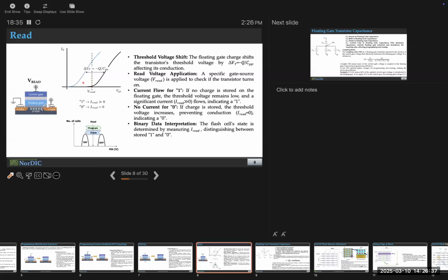Does that make sense? So just looking at the difference in current, you could sense it. And isn't that the story everywhere? Even for the ferroelectric transistor, that was the exact same story. For positive polarization, you have some current. Negative polarization, you have a different current. One of them is less than the other. Sure, you have a reference to select, to sense. Exactly the same concept. So in fact, the ferroelectric transistor concept tried to replace flash memory.